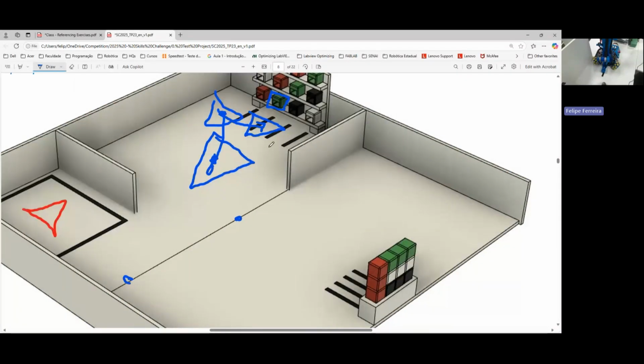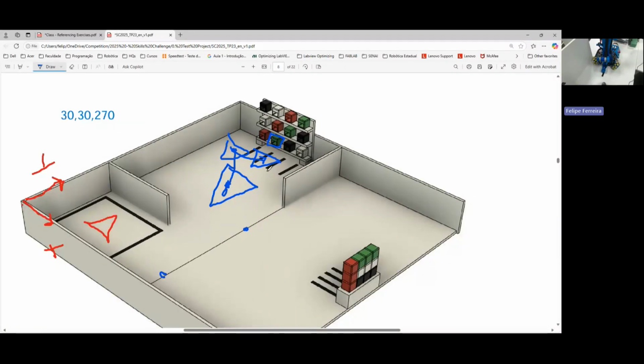This way, I can use the position driver for the whole task. So later, after taking the cube, I send to this position again. I send to this guy here. For example, I send to the side here. I use the line align function. I put the cube, then I come back to this point, then I go back to this corner. I use the sensors again. I reset the position. I go in front of the next cube, and all these movements will be accurate.